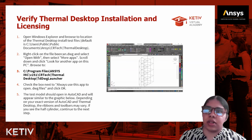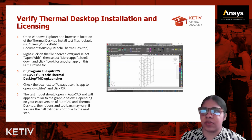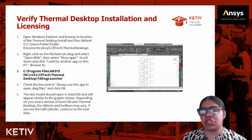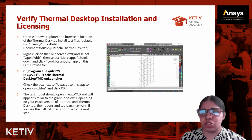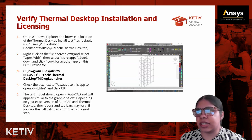So now you've installed all the prerequisites. You've also installed the Thermal Desktop package. We're assuming that you also have AutoCAD installed on your machine. The last step is just to verify that your Thermal Desktop product is actually working. Keep in mind that you should have an active Thermal Desktop license file that is added to your server. I did share a slide previously that shows which increments are included in your Thermal Desktop license file. So make sure you see that on your License Management Center before you verify the installation.